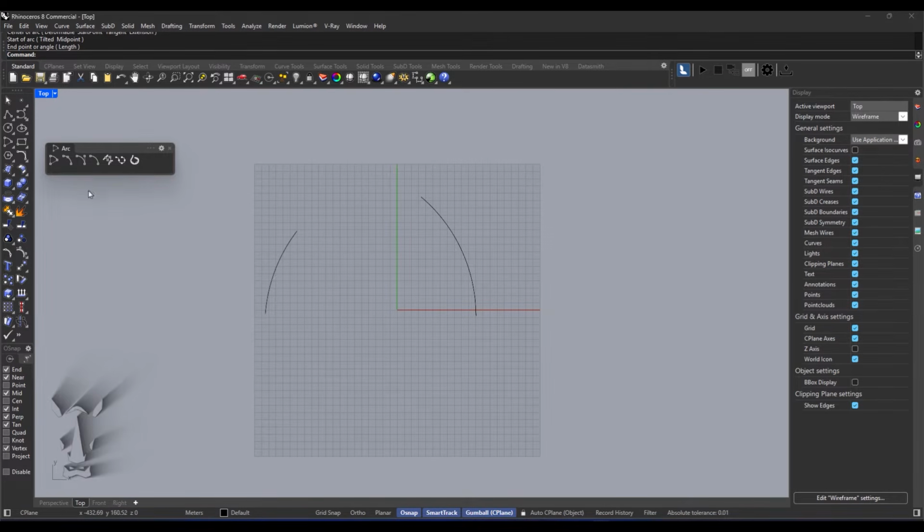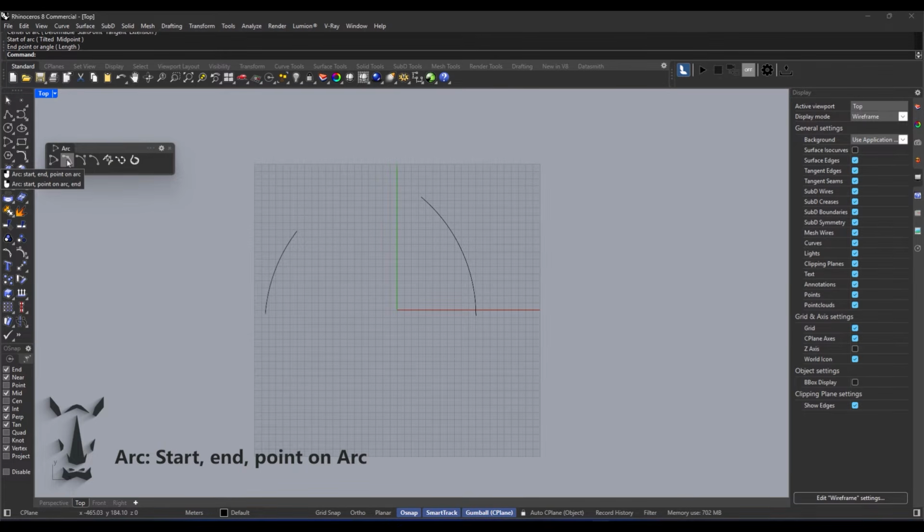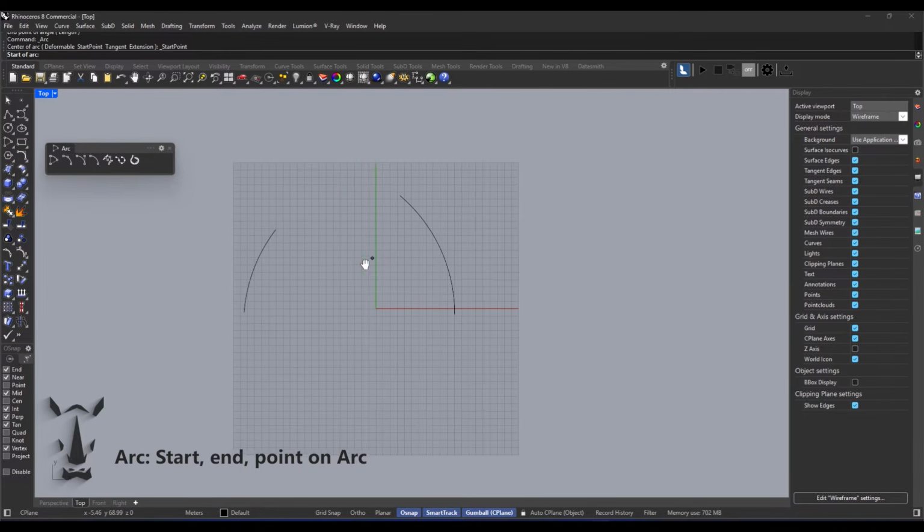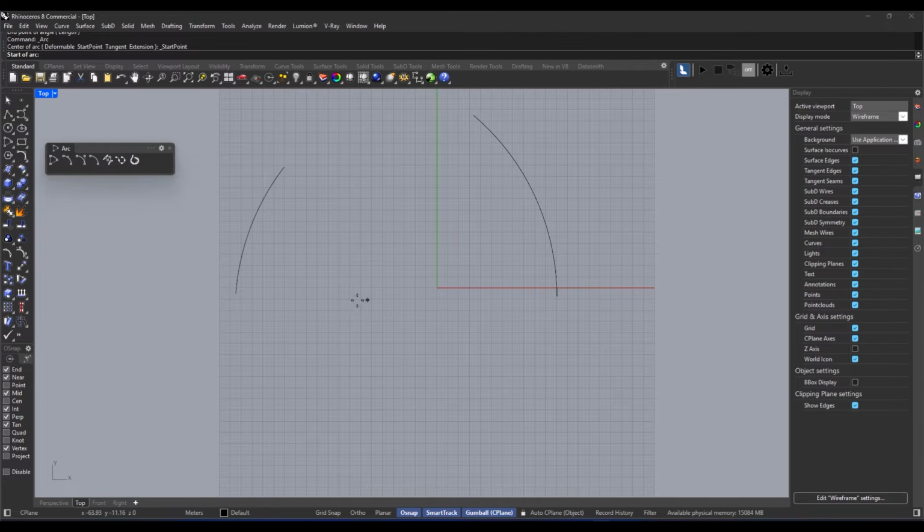All right, so here we go. We're talking about starting and ending points on an arc. First off, you draw the arc starting from the first end. It's super simple. For the start point steps, it's just 3 little things. 1, first, pick the arc's start point. 2, then you pick the arc's end point. 3, finally, click a location that the arc passes through.